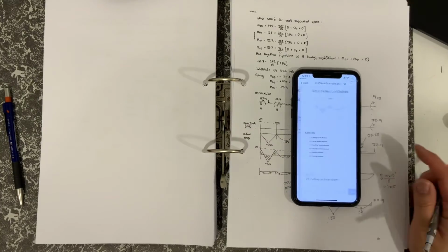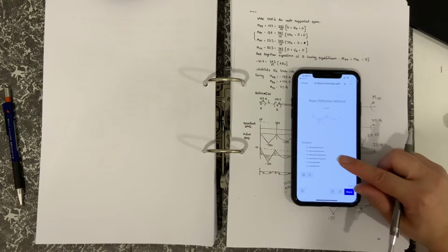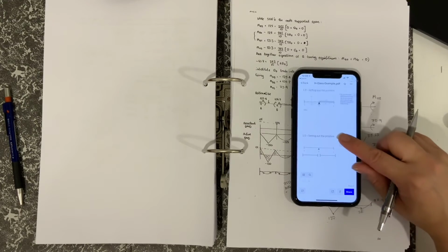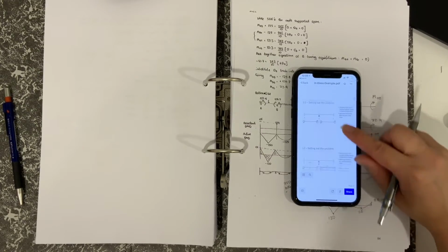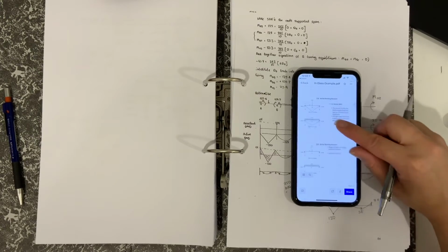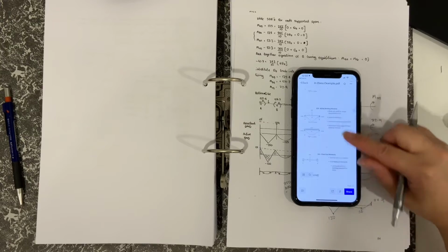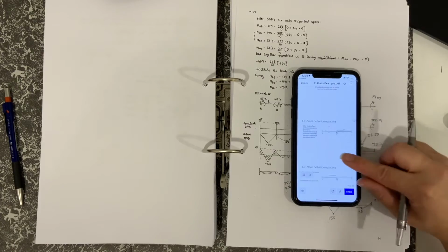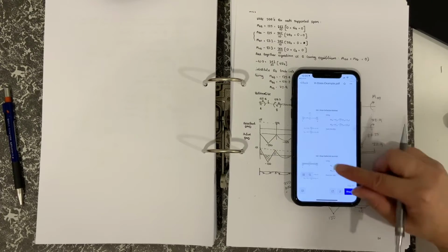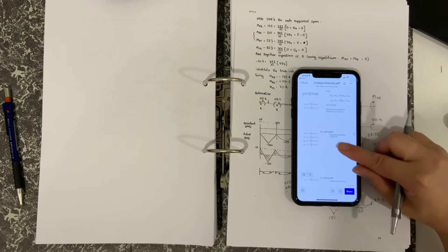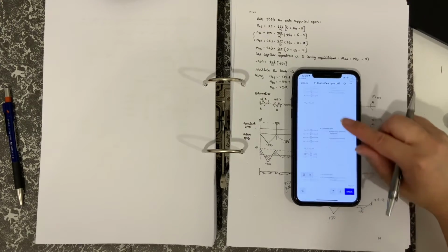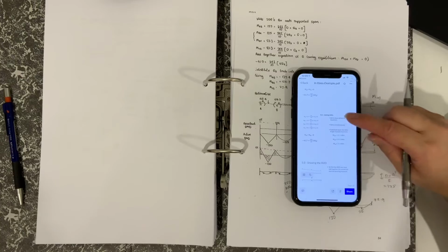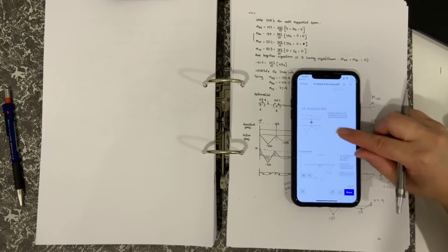So I got a student to write this out for me before. It goes on to quite a few pages, but it just goes through the steps that we've just covered, stepping out the problem, working out the fixed end moments, what the active bending moment diagrams are, where all the numbers come from, the slope deflection equations, adding them together, solving the slope deflection equations, but basically giving all the detail that you might feel you need the first time you look through it.